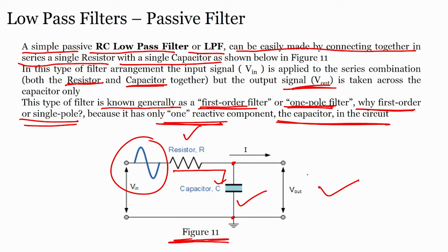And this kind of circuit also gives you a phase shift. If you really want to understand the phase shift, which we have studied in oscillators, right, 1 RC will give you a phase shift of 90 degree. If you adjust the value of R and C, you can change it to 60 degree, right. We have studied RC oscillators.